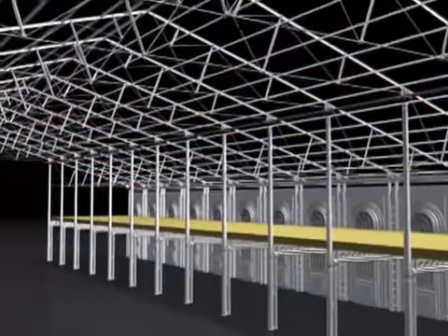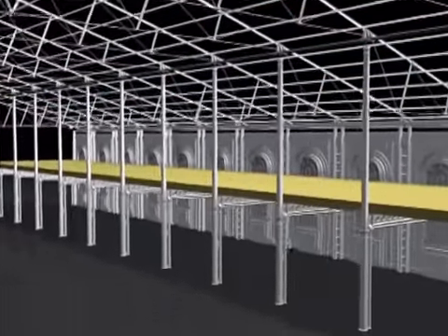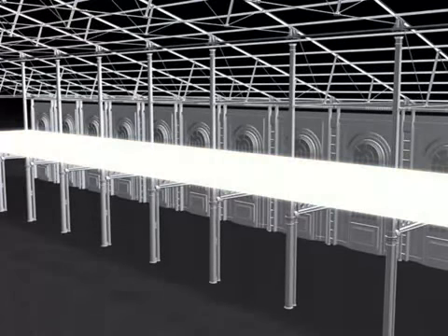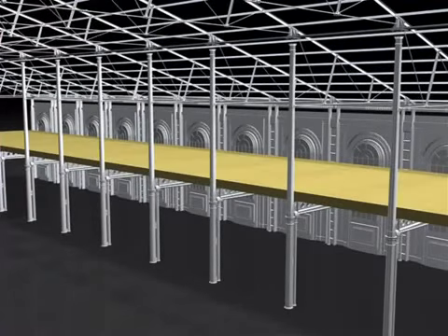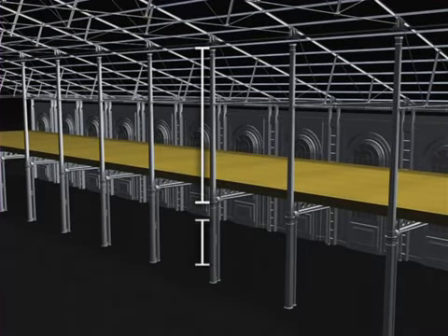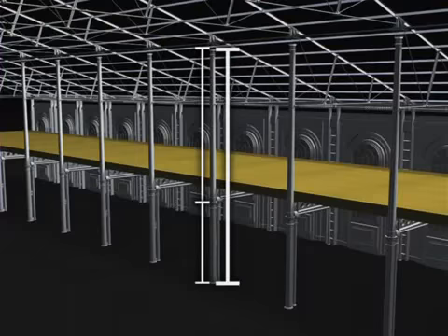In the case of the specific geometry of the Watervliet Arsenal building, the addition of that lateral bracing point at the first floor gallery had the effect of increasing the buckling strength by about 250%. In general, the strength of a column is determined by the length between points of lateral support, which in many cases can be considerably shorter than the overall length of the column.